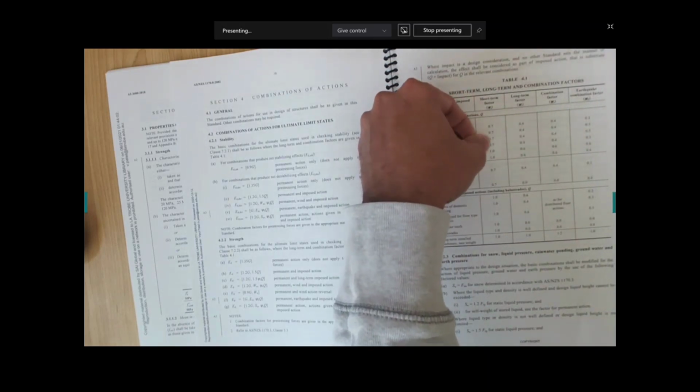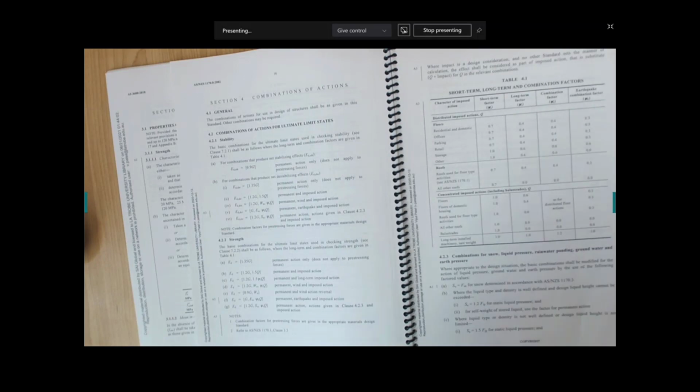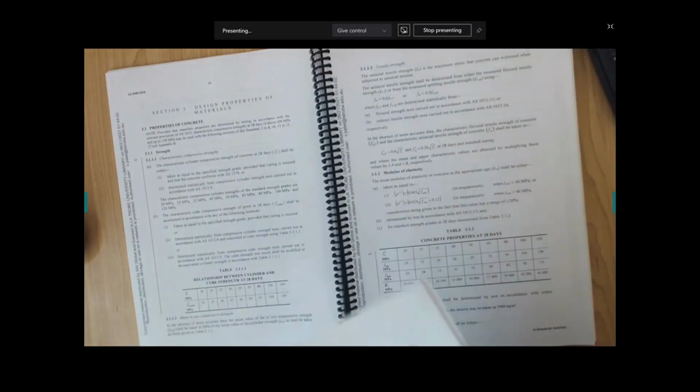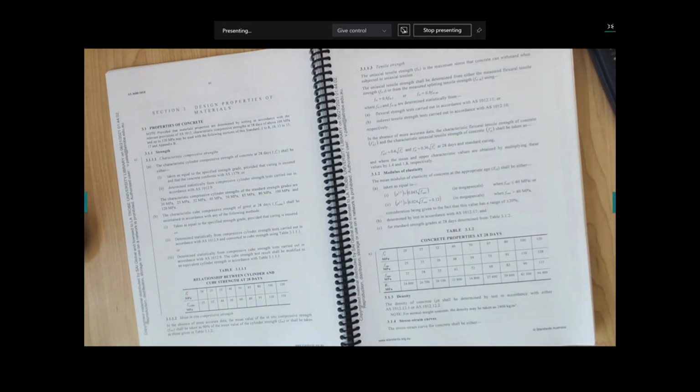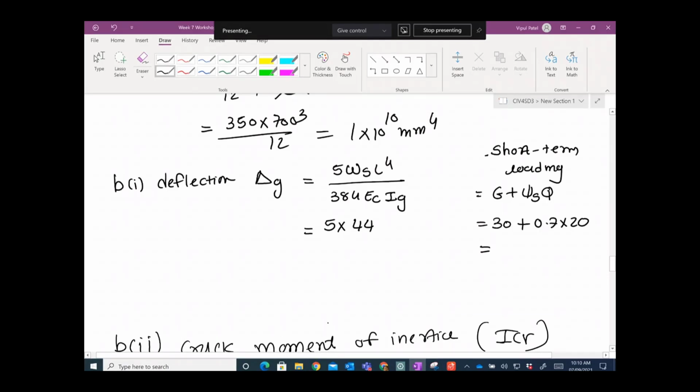It means that when you open your building on day one, you may not get all the users that you predicted. On day one the building will not have those 20 people, meaning you may not get those 20 people in the first minute, right? You might have some inspection or some guests, but you may not have it. So you can have 30% reduction. Therefore it just multiplied by 0.7 and gives 44 kilonewton per meter.